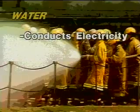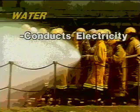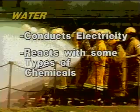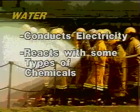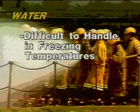It conducts electricity, so it should be used with extreme caution when fighting electrical fires, and only as a last resort, preferably after all electrical equipment has been turned off. Water reacts violently with certain chemicals, such as peroxides and carbides. It's difficult to handle in temperatures below freezing.